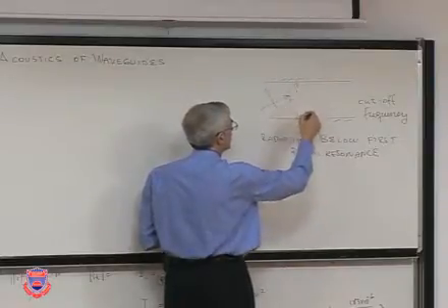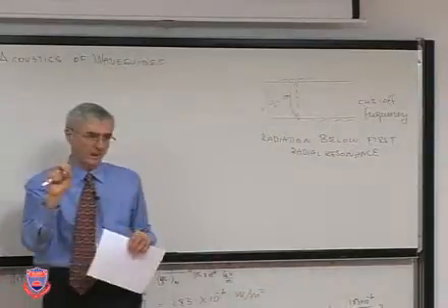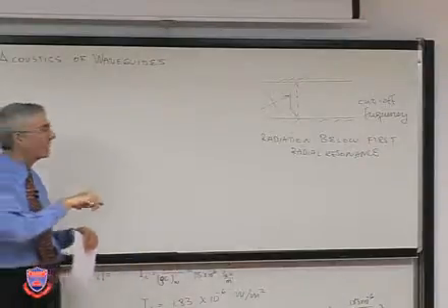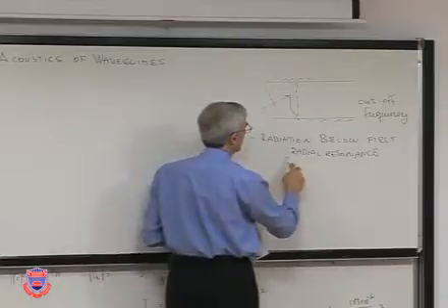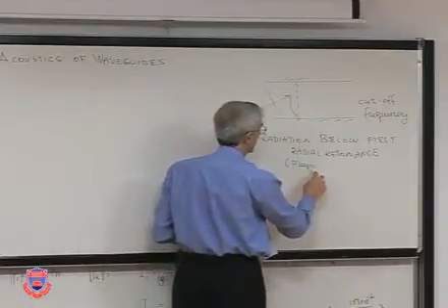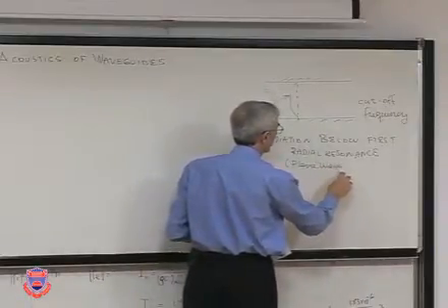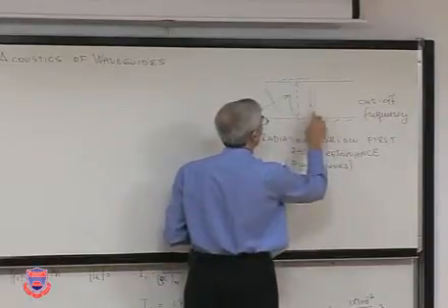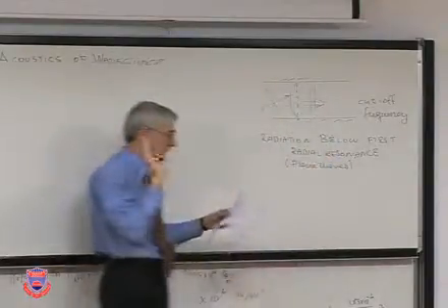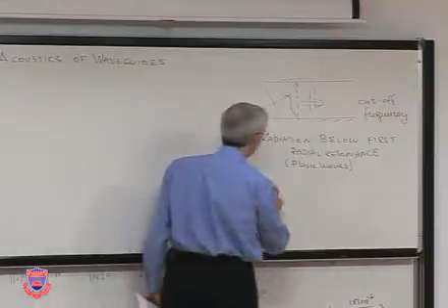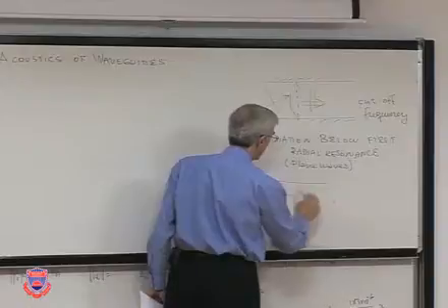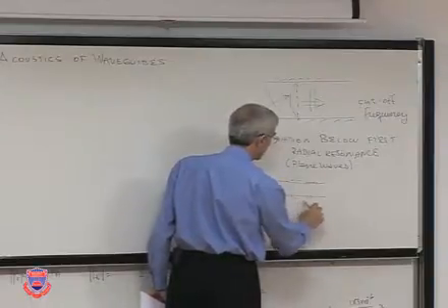And the first resonance here is the cutoff frequency for that mode. And below first radial resonance, it's all plane waves, just like we have seen before. Sound will be radiating straight down. Well, what happens then if you have a pipe that's flexible?